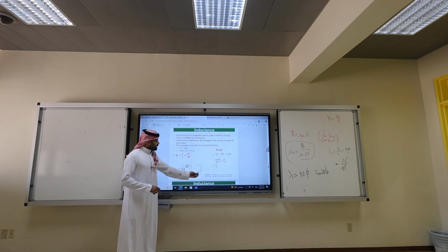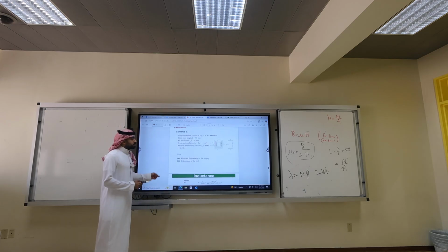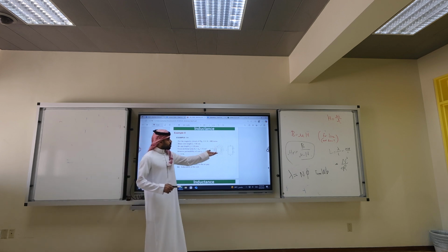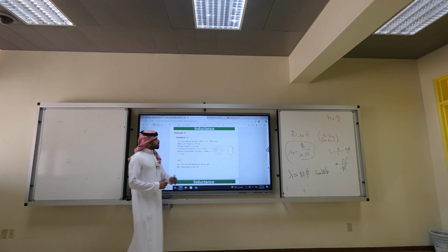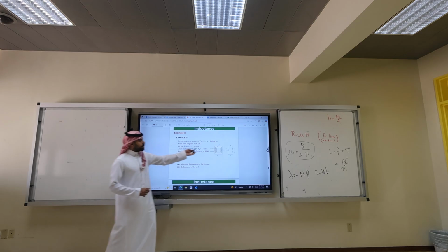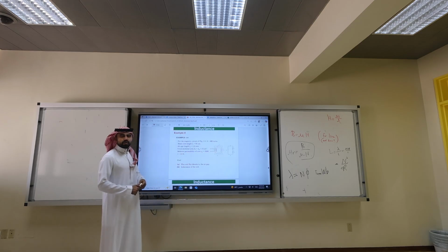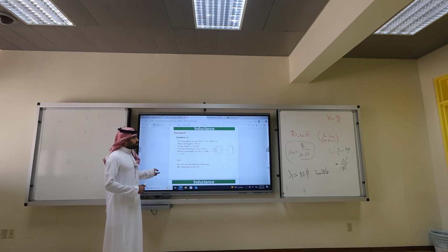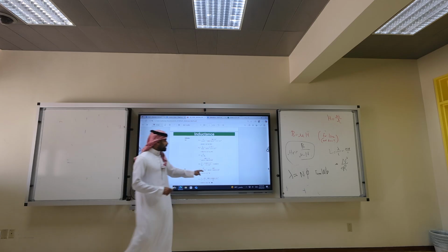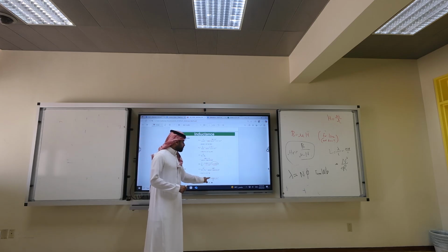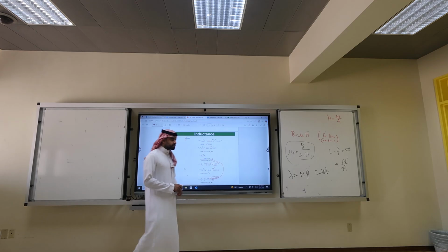So, modeling it as an inductor would be a problem. For example, in this problem he tells you the cross-sectional area of the core and the air gap is the same. So did he ignore fringing or not? He ignored the fringing. If you do the calculation, this is a typical problem: two reluctances, Ni over R equivalent. For I equal to 1, for 300 or 400 turns, he calculated the flux density to be 0.4 Tesla and the flux itself, which is this quantity, to be 0.6 times 10 to minus 3.